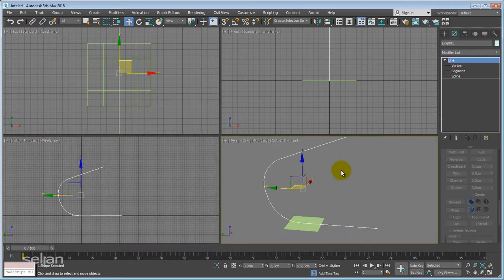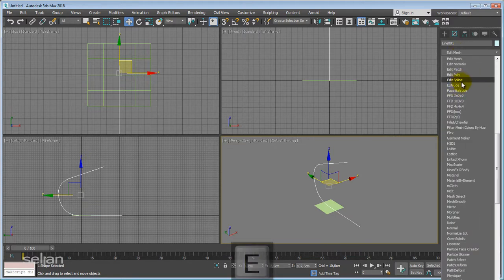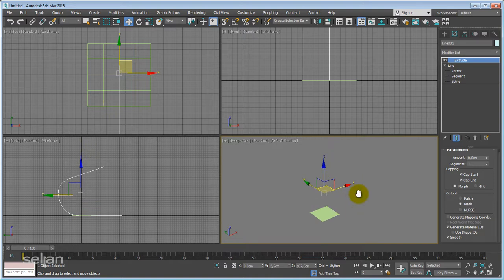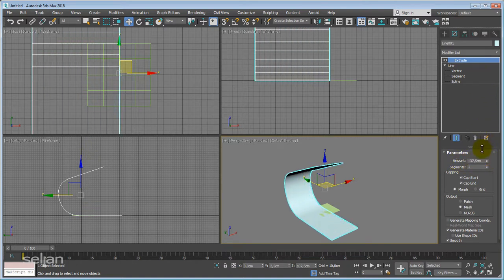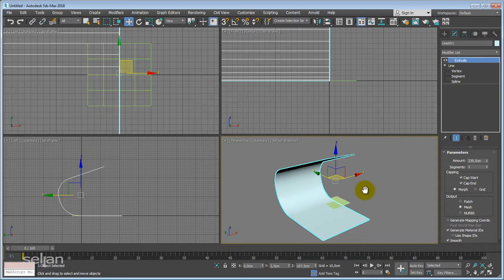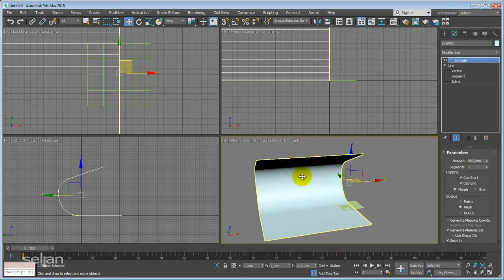Okay, now make it 3D. This one is just a 2D shape item. So line is selected, modify list, and extrude is what we need. Okay, the model is disappearing because it's not a line anymore, but it has no volume of any kind, or has no surface at all because amount is 0. So don't be scared. We have it, but it's just not there. I will set it to 400. That's 4 meters. That's pretty much fine.